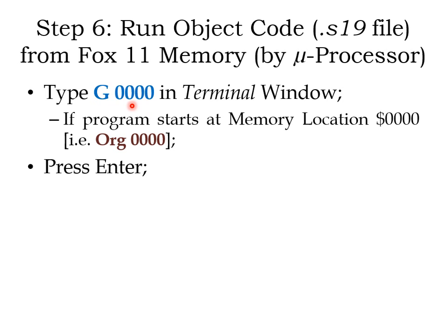Because in the run instruction, you always indicate the address where the program has started. And how do you know it? You will know it from the ORG instruction, I would say ORG directives. If you look at these, you will know exactly where the program started, and all you have to do is mention that address in the instruction when you run. So this address will be varying based on the program, right? So make sure you see and use that instruction.